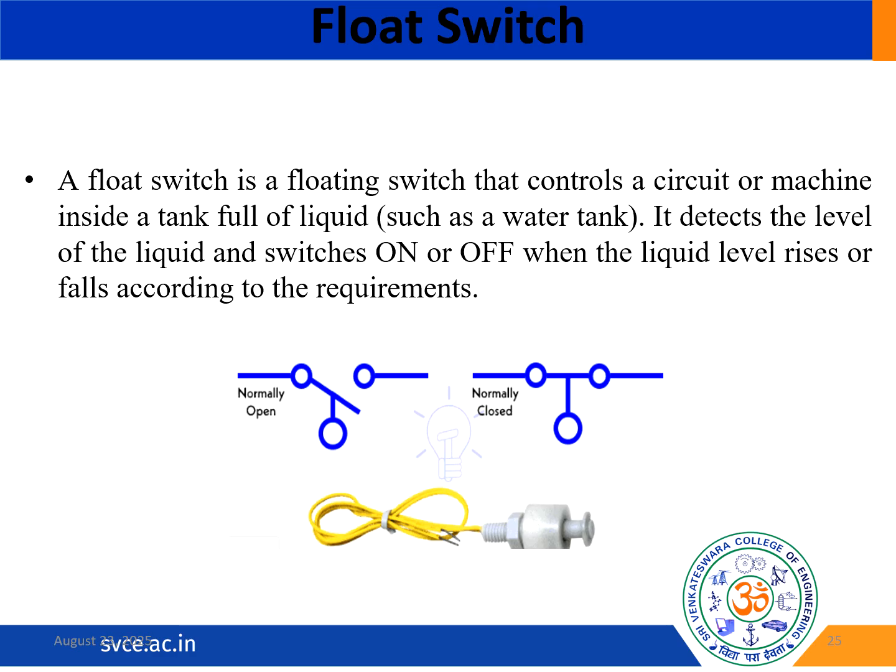Okay, so when the liquid level rises, what happens? It reaches a predefined threshold. That float movement activates or deactivates the internal contact, thereby switching the connected circuit either on or off. This enables automated control of pumps, alarms, or other machinery based on real-time fluid levels.